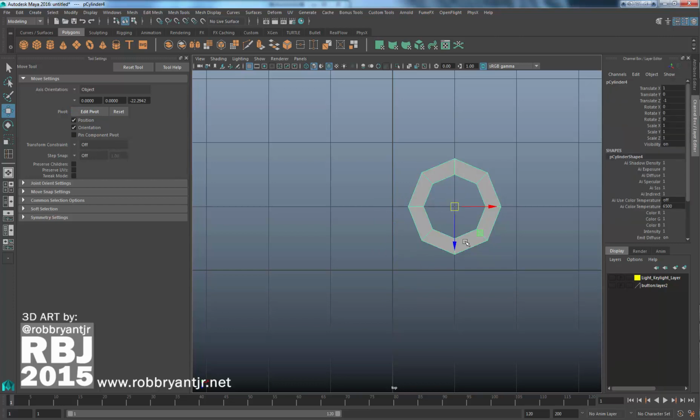group this. So if I press Control G, it groups it. But the group is not what I'm after. What I am after is the exact, accurate location of the pivot point being at the 0, 0 space in the world. That is what I'm after. Great. So now that I have this